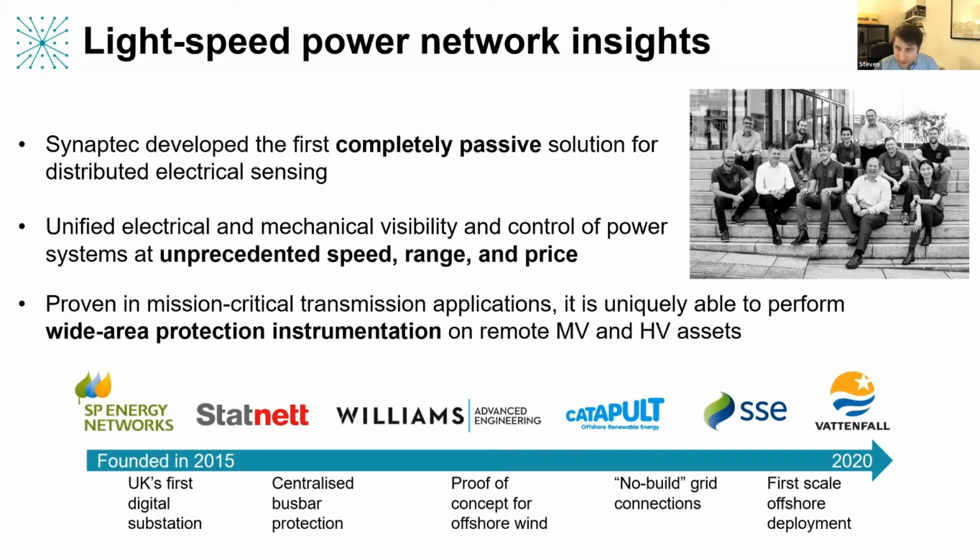Just for a little bit of context to set the scene, Synaptec is a vendor of sensor systems, and we're based in Glasgow in the UK. What we've created is a unique passive sensing technology that's able to bond multiple sensor types, including VTs and CTs and other types of sensors, onto a single optical fiber. This means that we can distribute many sensors over a wide area using a single optical fiber, and then deliver that data to a central location wherever it's needed. This is quite powerful, and it's certainly unique in the industry.